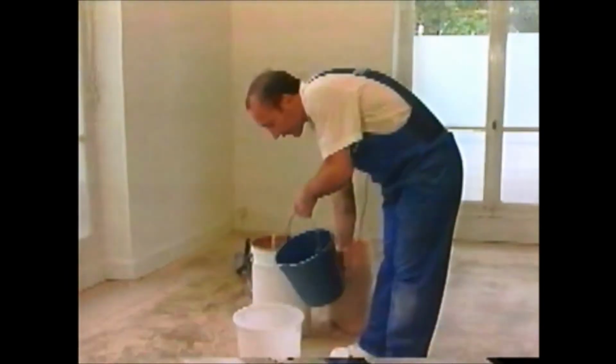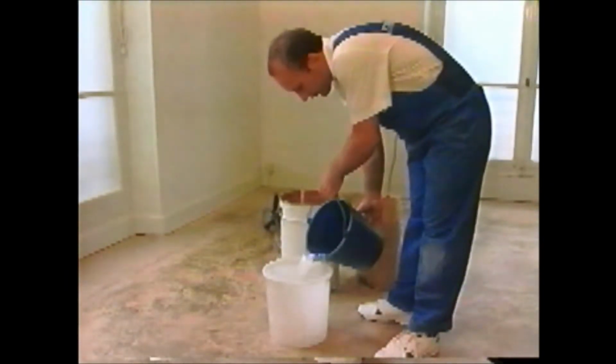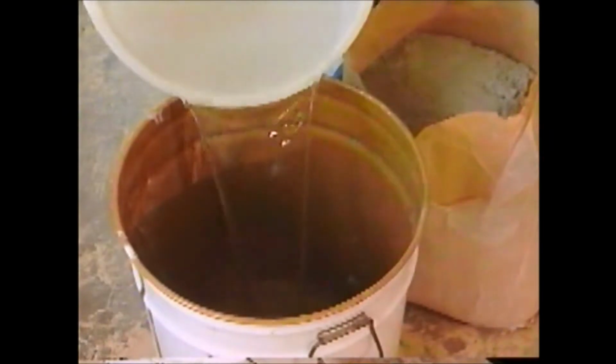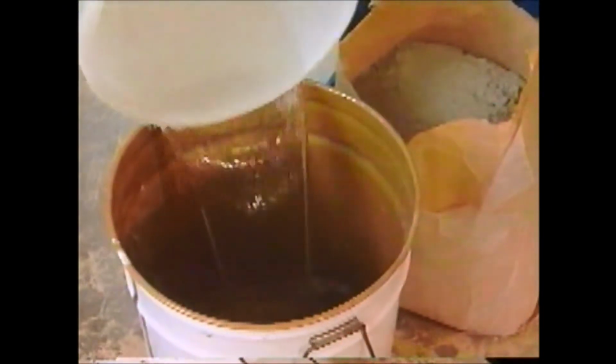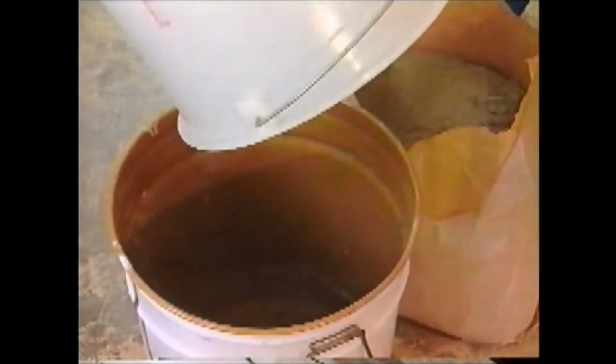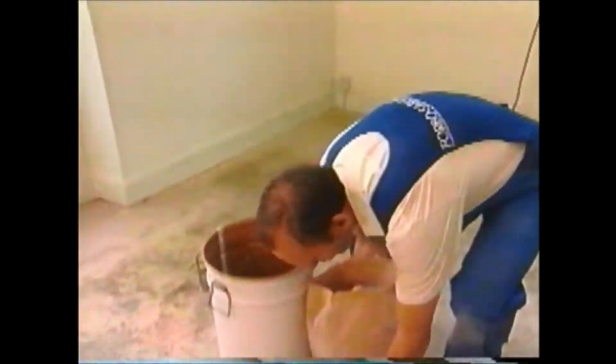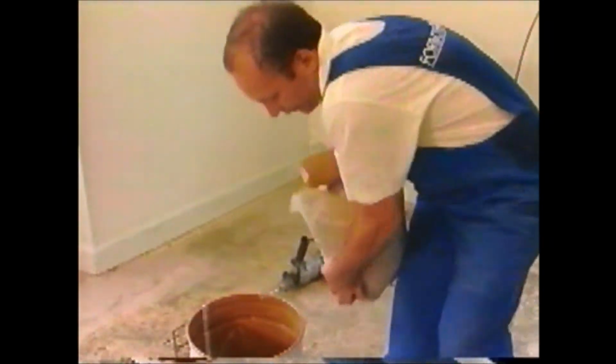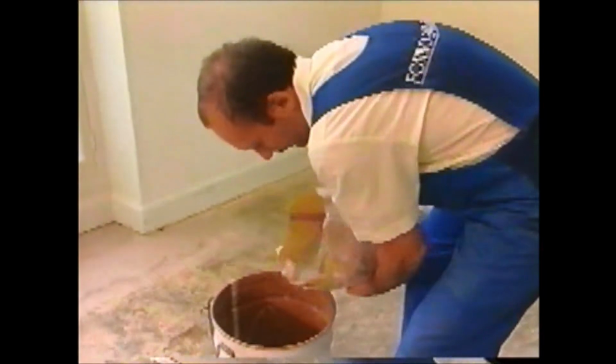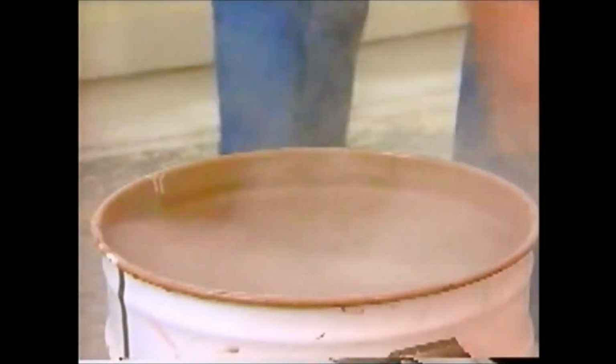The finish coatings must be carefully mixed with special attention paid to the amount of water, the water temperature, and the order of addition of ingredients. The water must be clean and between 8 and 20 degrees Celsius to permit the powdered additives to act correctly in the coating. The water will be added first, followed by the additive, and then the powder, and then mixed in the mixer.